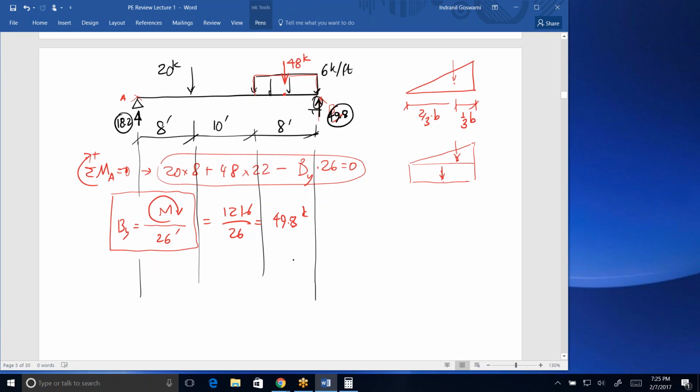this is something that helps you line up the appropriate sections with the loads. So it'll go up 18.2. For the shear diagram, simply follow the load, track the loads as they are. The shear diagram is tracking these kinds of forces, right? This is your shear. Anytime you see forces like this reaction, 18.2 will push the shear diagram up 18.2. Then there is nothing happening, so the shear diagram stays the same. Then you have a 20 down, which pushes the shear diagram down by 20, and that'll come to minus 1.8. And then nothing happens, so the diagram stays flat.